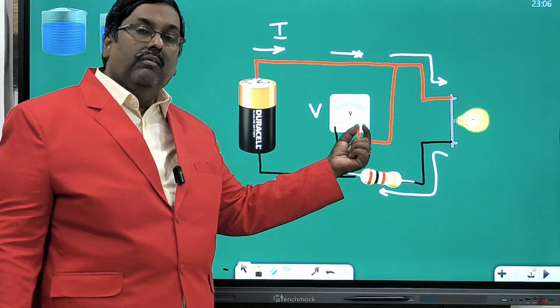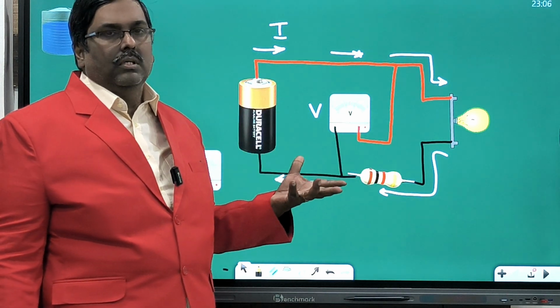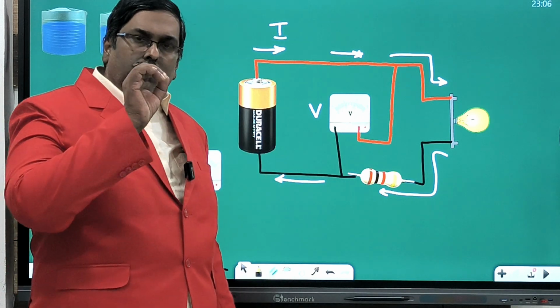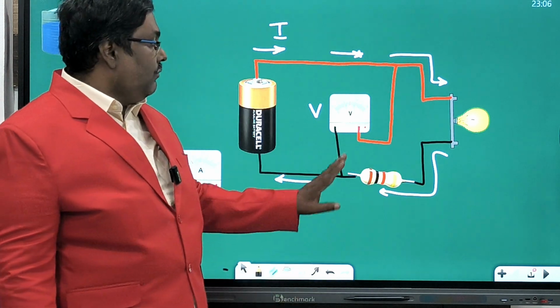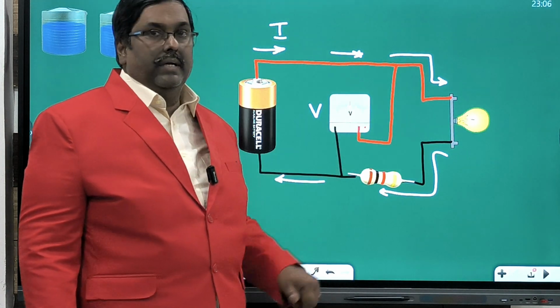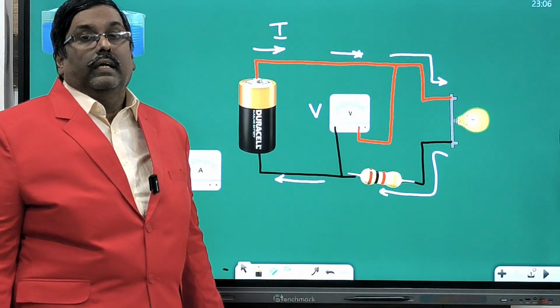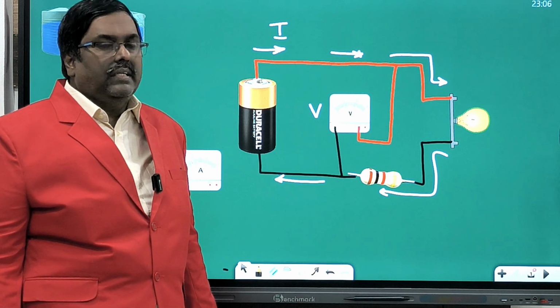But this value we are putting is very minute, 0.01 ohms like that, very minute. If you have less resistance, there is a very minute change in the current. So if you want to measure the current with the voltmeter, we have to put one low ohms resistance in the negative side, not in the positive side. Put it in the negative side, that is better.